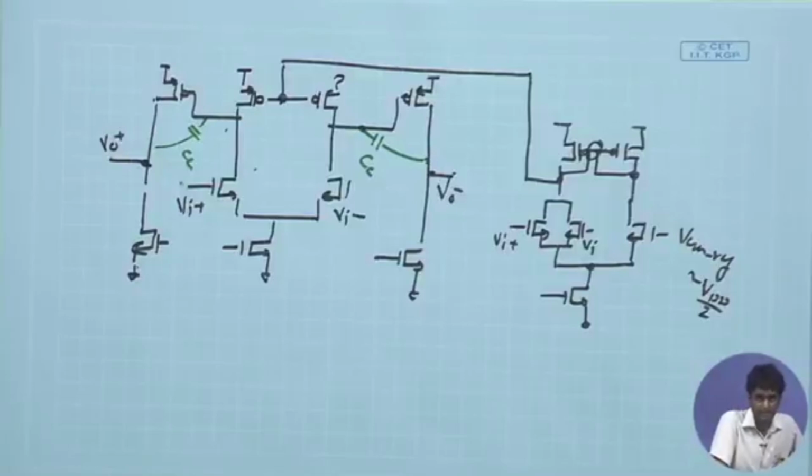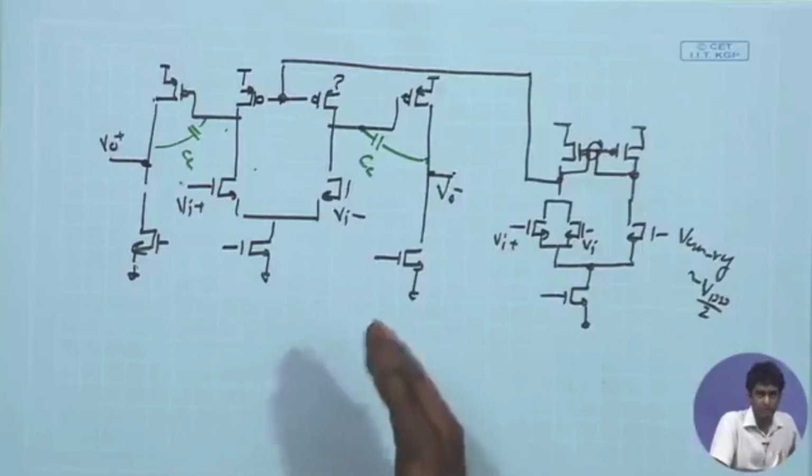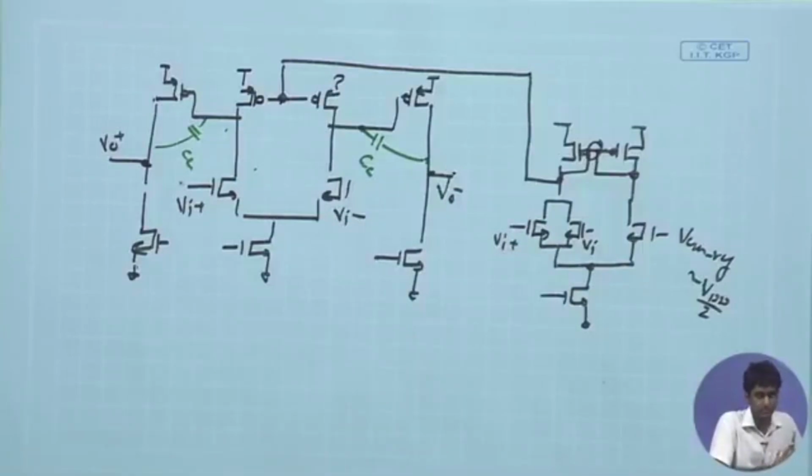That is what we discussed last time, and therefore, we explored the alternative where we can have two isolated loops, two different loops. And then we just now discussed the transistor level implementation of both the loops and the stability considerations, looking at the conflict between the two loops and making sure that the stability analysis of one of them is not influenced by the other. So, this is an important conclusion that we just arrived at.